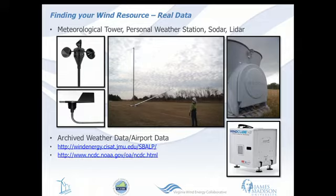They'll put a series of these on anywhere from a 50 meter to an 80 meter tower. 80 meter is usually what the large scale developers put up now, and they'll put those out at their site for ideally 3 years and just start taking data, and then analyze the data as it comes in to profile the wind resource that they're looking at harnessing. Some other methods do the same thing, as you might imagine, putting up an 80-foot temporary tower is not an easy task. So there are 2 new technologies.